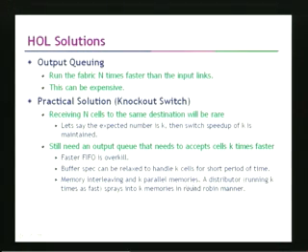What you can do really is use memory interleaving and k parallel memories, and finally a distributor which runs k times as fast, and it sprays cells into the k memories in a round robin manner. So it's like there are k parallel memories and then the distributor. Whenever the k cells come, this distributor will have to run k times faster, and it sprays these cells into the memories in a round robin manner. So you can use this principle, a distributor and an interleaved memory, instead of going for a faster FIFO which runs at a speed of k times more.